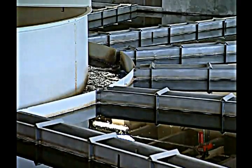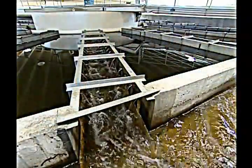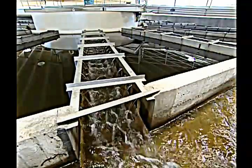These variations in design are generally used to reduce detention time, increase flow rates, and raise capacity within a smaller footprint. The underlying process is the same: you have water flowing in one direction and particles flowing in another direction. And you settle the particles by gravity, and they get thicker at the bottom. They turn into sludge, and you remove the sludge.